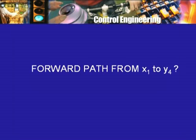y4 I want in terms of the two input signals x1 and x2. To find the coefficient of x1, I have to identify forward paths from x1 to y4. There may be more than one. In fact, there is more than one. For example, from x1 to y4, I can go from x1 to y1, I have no alternative, and then I can go over to y4. The gain of that forward path, now we have got so far maybe P1, P2, so we will call it P3.